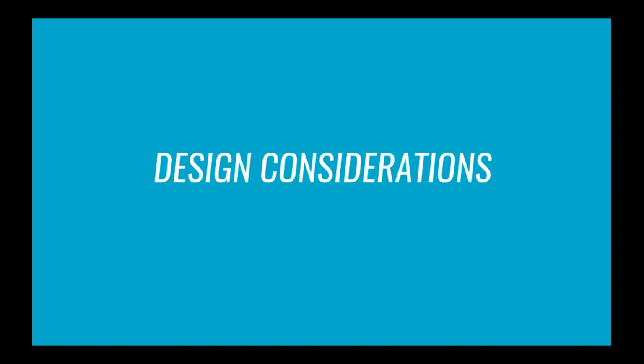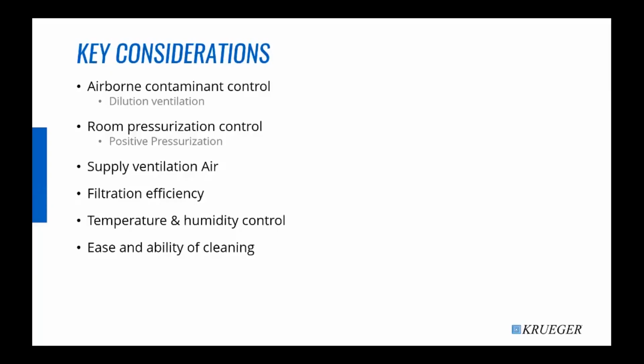Some of the key considerations for HVAC air distribution systems are that they're required to play many different and unique roles in critical environment spaces. Operating rooms are obviously critical spaces. We want to make sure we have clean air and a clean environment. Pressure control varies by space type as well. For example, OR rooms generally require positive pressure, while labs generally require negative pressure. In an OR room, positive pressure will prevent contaminants from entering the operating room.